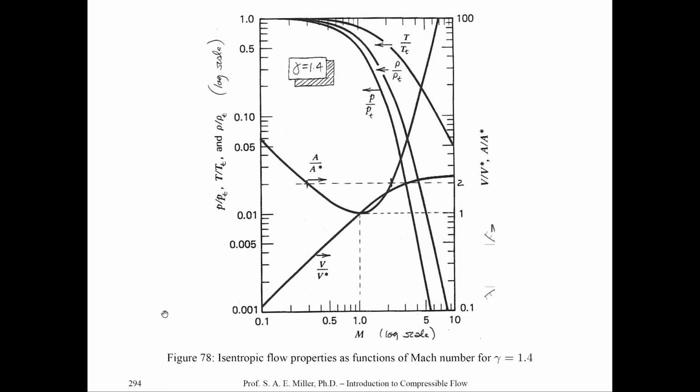So let's look at how each particular function varies. Let's first look at the area ratio. The area ratio, the area of the inlet of the converging diverging duct divided by the throat, goes as this curve here. It's plotted and defined by the geometry. As we increase the area, it rises up and goes to infinity, for the analysis at least.